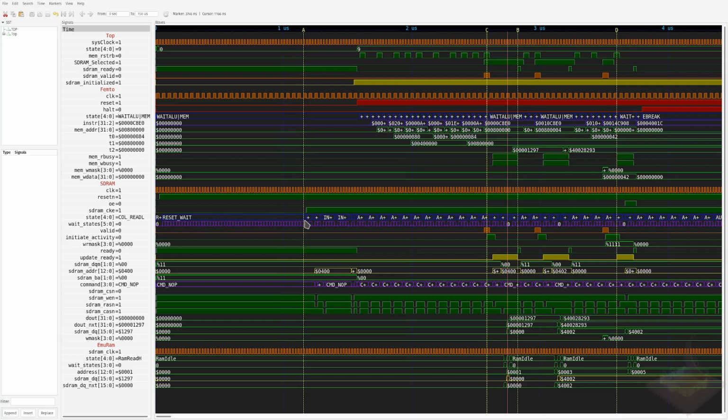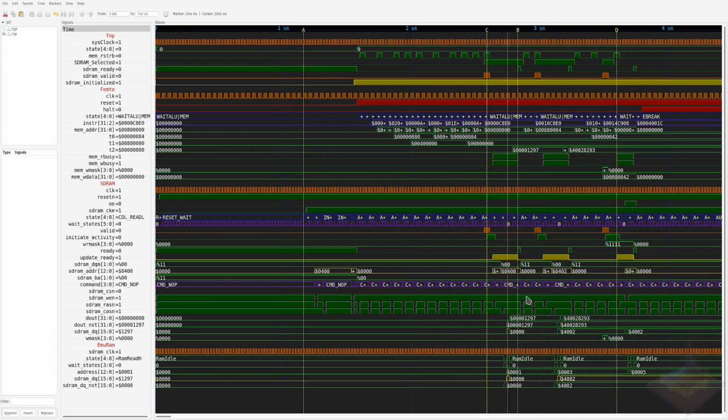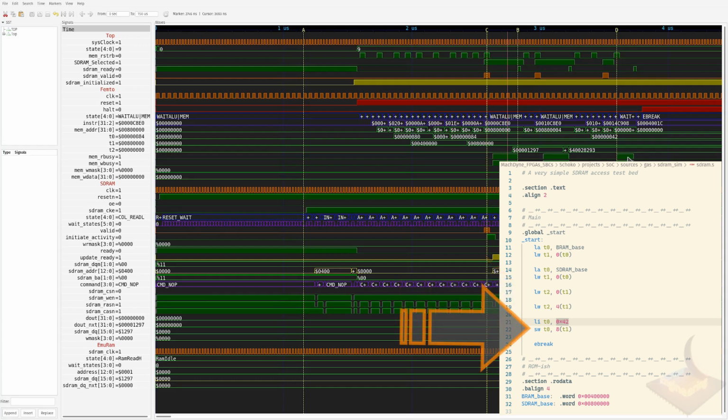And as soon as it's done initializing or powering up, if you will, it goes into its initialization sequence, and that's what all these things are. We'll zoom in a minute to take a look at them, but we're looking at it just from the high level. We have activity here during the instructions. The Femto is executing that little program, and part of it is accessing the VRAM and doing things with it. That looks like that's working there. And then we hit that section of code to make 2 reads and 1 write, and that's what we're seeing. So far it's looking pretty good.